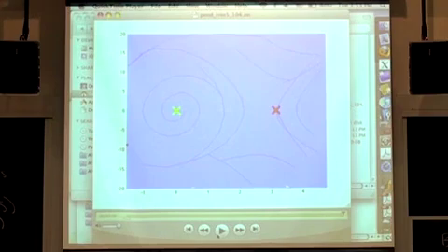Could you factor in actuator limits into the Lyapunov function? Yes. So okay, actuator limits in the Lyapunov function are harder. What you do is everything is based on a Taylor expansion of the dynamics around the nominal. So a hard limit, if I linearize and I don't see that limit, then I'm not going to know about it.